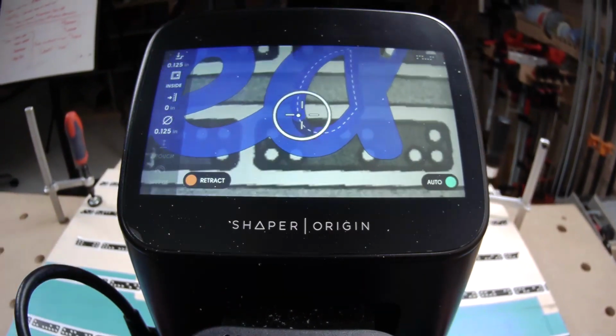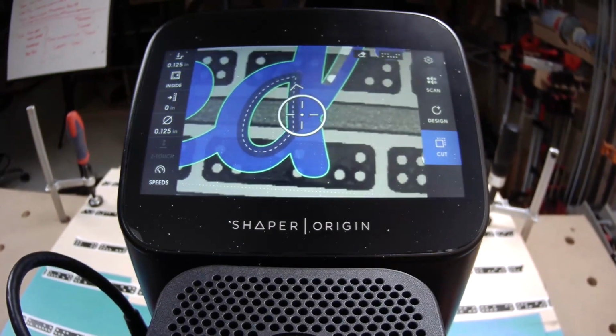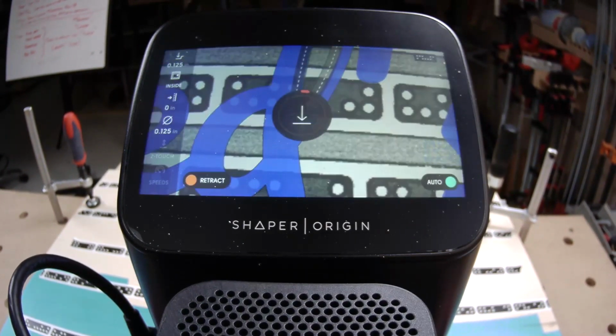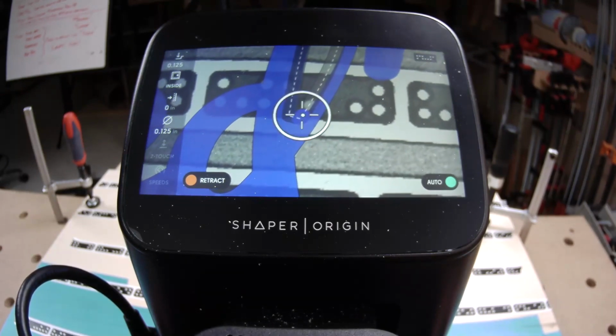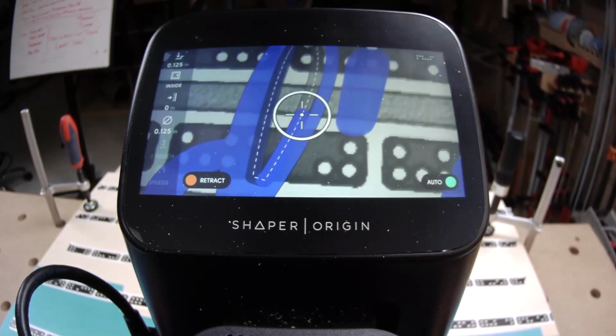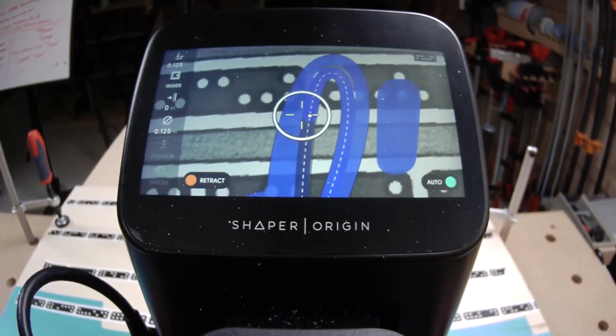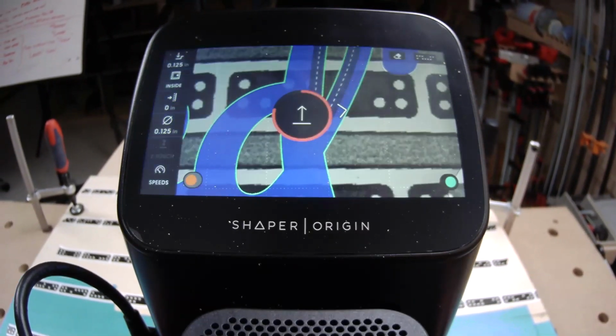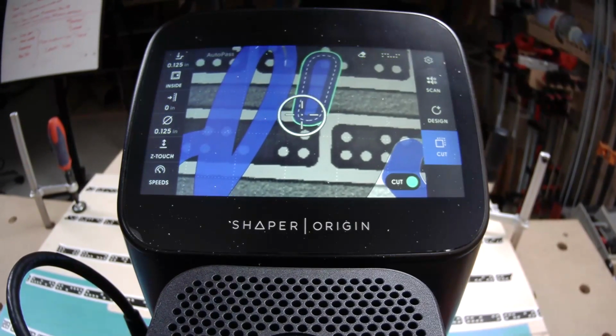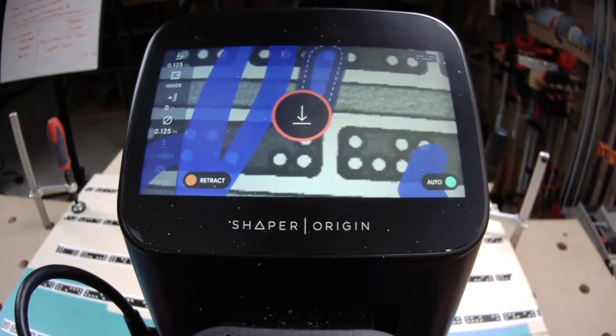When you're taking a thicker cut, then you're definitely trying to push a lot more waste sawdust into the cut with that down cutting router bit, and it can be hard to manage and or dangerous. But really love down cutting bits, especially really small ones like a 1/16 of an inch for inlay and marquetry.